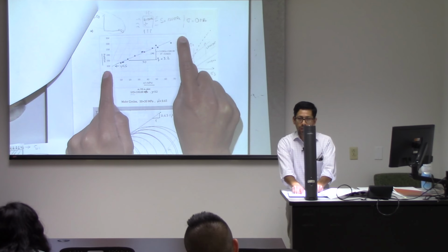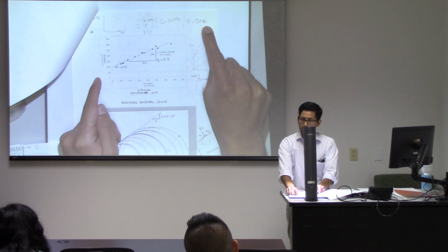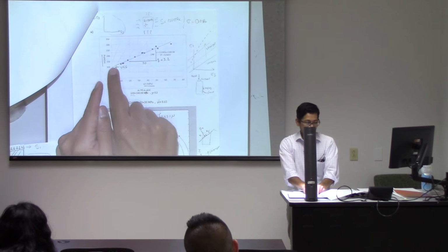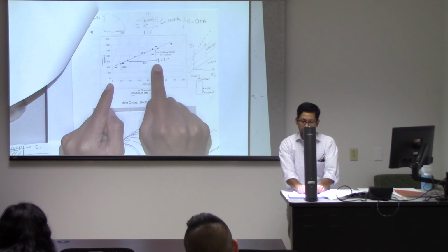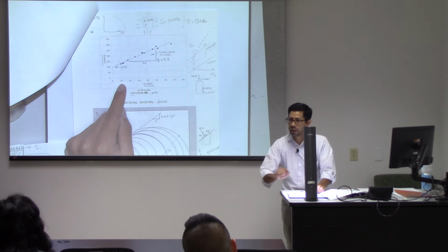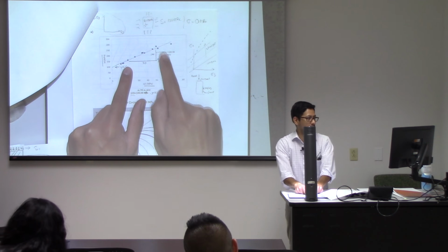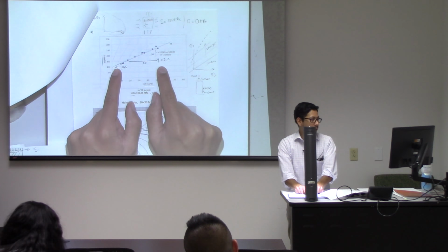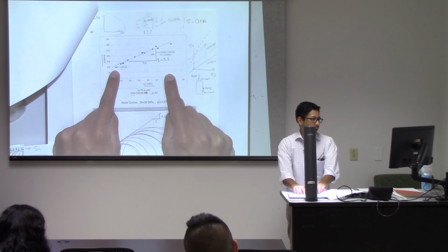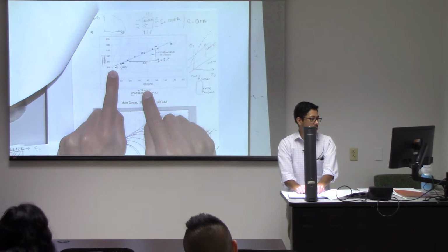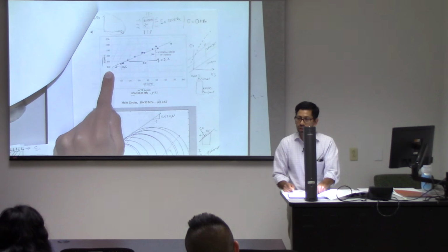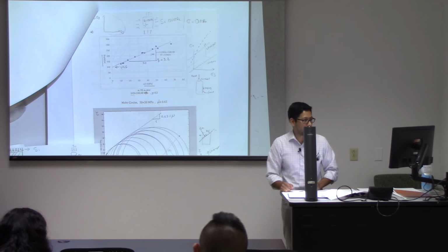If you're doing this in an exam, just get a ruler, draw a line, just eyeballing what you think is the best fit, find the intercept, calculate the slope to the best of your abilities, but you don't have to run a regression line on paper, okay? Don't worry about that. Just tell me more or less what the slope is, and from here you're going to be able to get your equation for the failure line, which is going to be, in this case, 100 MPa plus 3.2 times sigma 3. And that's everything that you have to do.